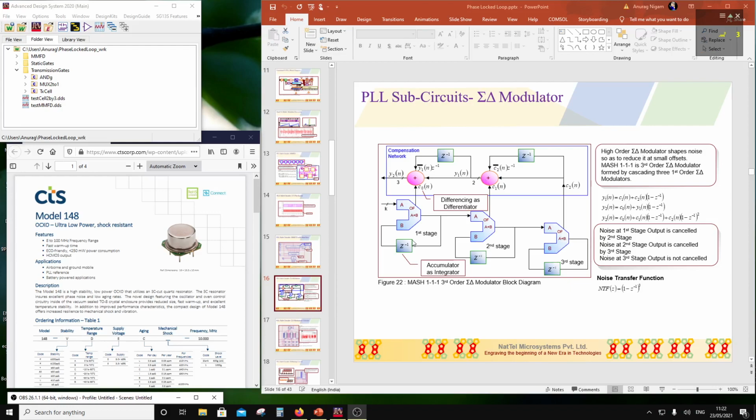Now here I'm going to first design a 1-bit accumulator, and then I will do a 12-bit accumulator. I can do a 16-bit accumulator if I want, but because this circuit operates at a low frequency, you have to run through that many 2 raised to n cycles for this PLL to stabilize.